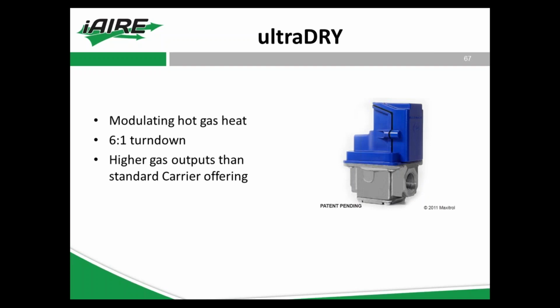They also add to every ultraDRY unit that has gas heat a modulating gas heat valve, which has a 6-to-1 turn down, fully modulating.